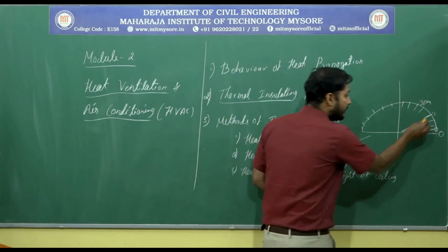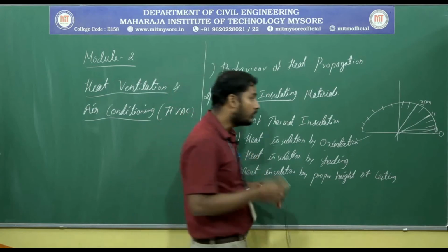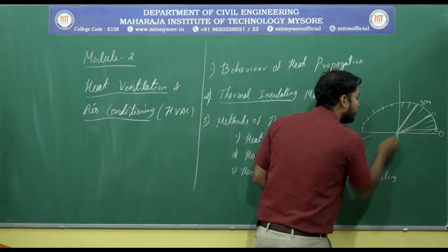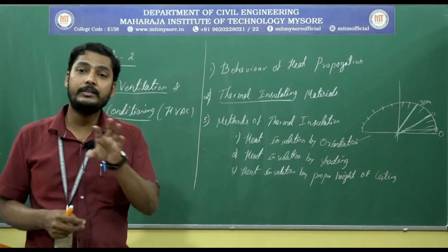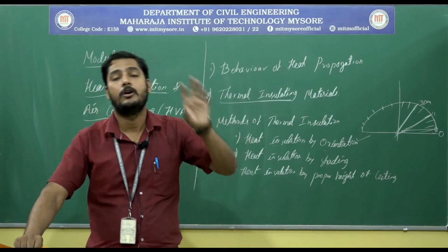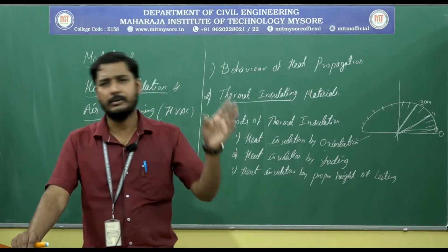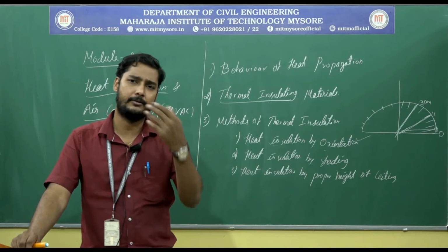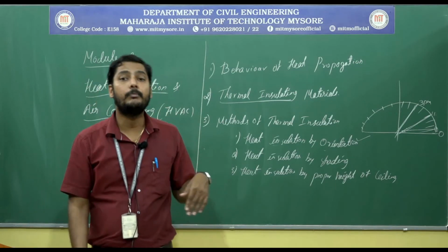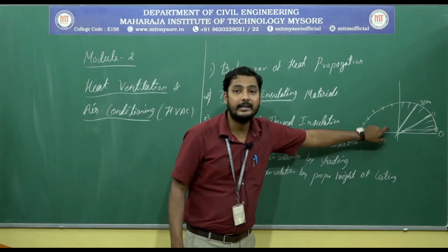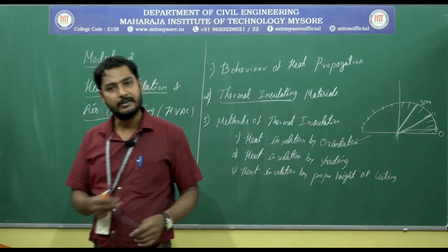So in that particular duration, what should be the angle of inclination we need to make towards the components of the buildings? We need to consider the main halls or bedrooms or kitchen areas or whatever building components, whether residential or institutional. By orienting the building itself, we can in turn minimize the heat liberated.